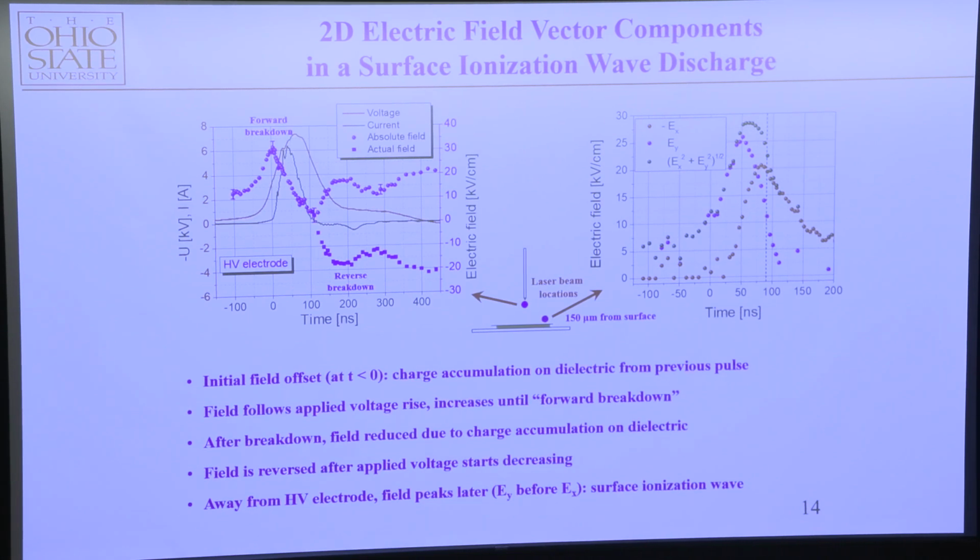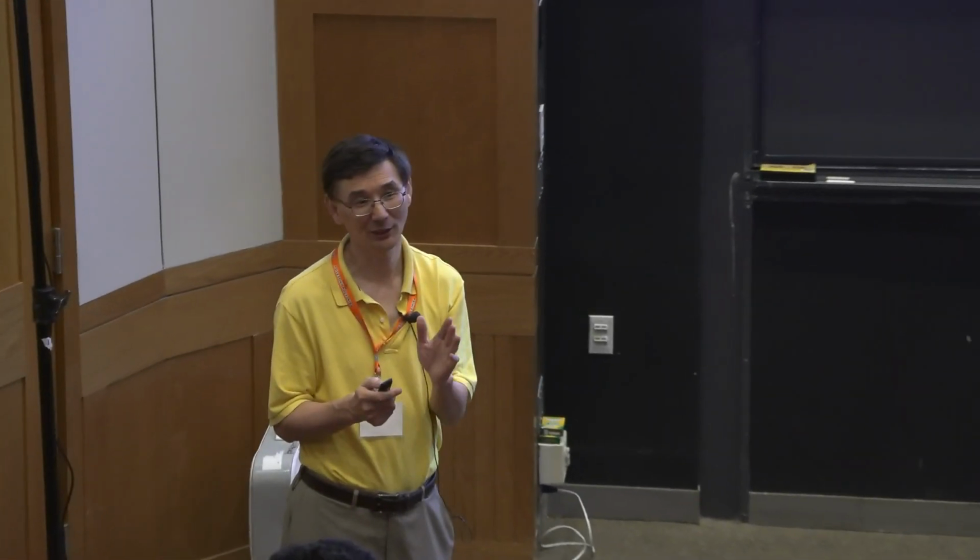This is typically very important for silicon manufacturing. If it was an ion beam, you try to cut the silicon, but you find the ions are building up on your surface and affecting your next ion coming in. That is dramatically hurting your accuracy, whether it's 2 nanometers or 1 nanometer. See what I'm saying? So it's very important to measure this electric field.